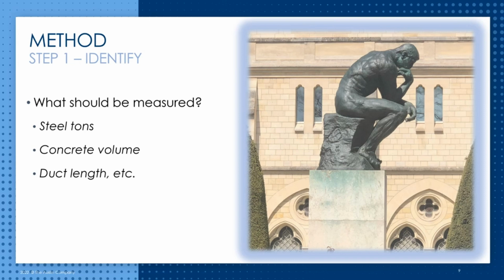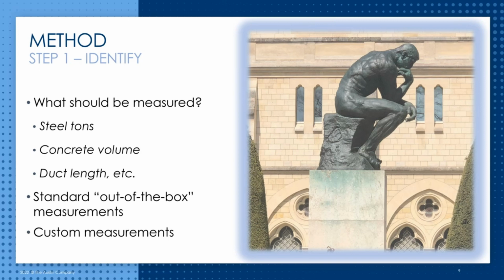Each design build team member will champion different aspects of the virtual model, which should be measured. Note that programs such as Revit have auto-labeling schemes to identify general components, such as columns, beams, and walls. These are standard identification categories offered out of the box. You will often find, however, that what you are interested in measuring requires a custom identification scheme, which goes beyond the standard bins.